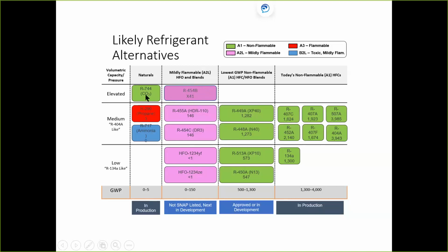And then you have your different refrigerants here, your CO2, your 290, which is propane. The difference in this propane, by the way, than the propane used for your grill, is that it's going to be without a stench, with no smell, in other words, okay? So that's brought some concern up because it has the same flammability, but when we walk into a mechanical room, a technician might not know it's around them. So what's that going to look like in the future for us? Will we have to have maybe some kind of alarm strapped around our knee?